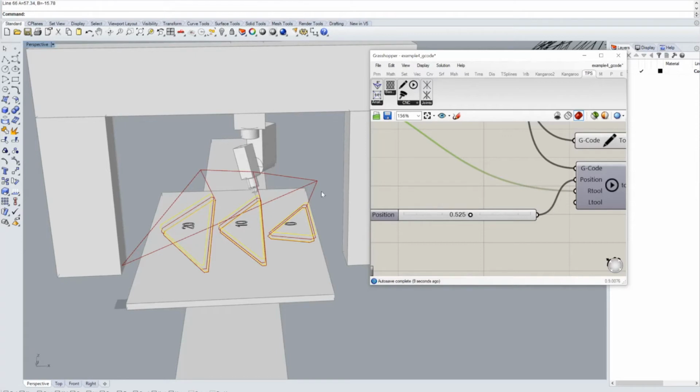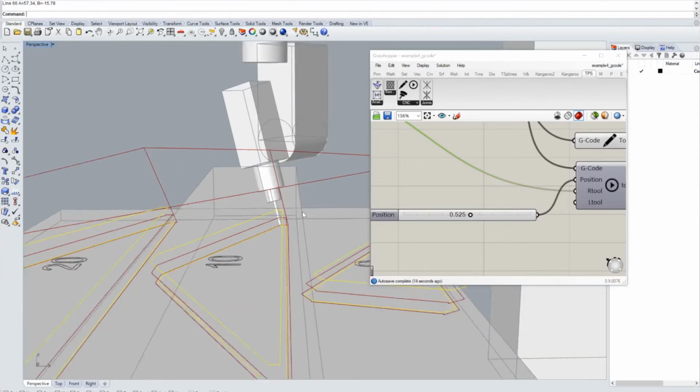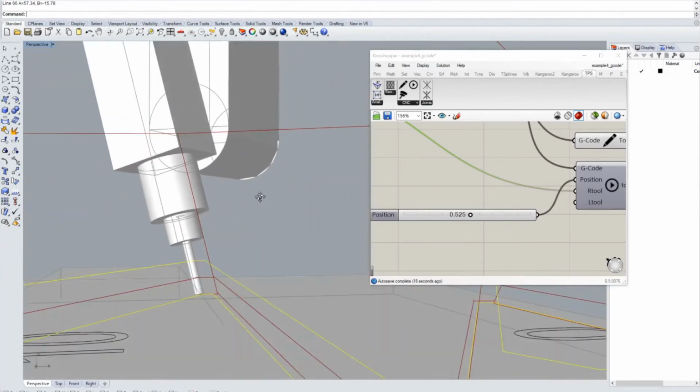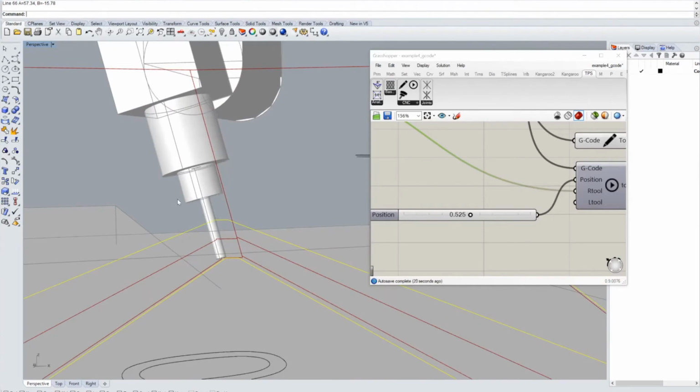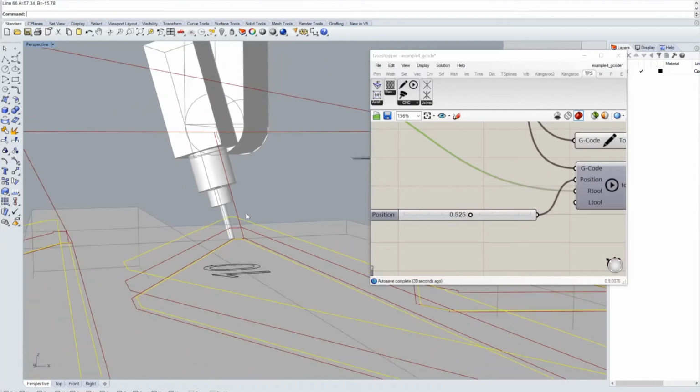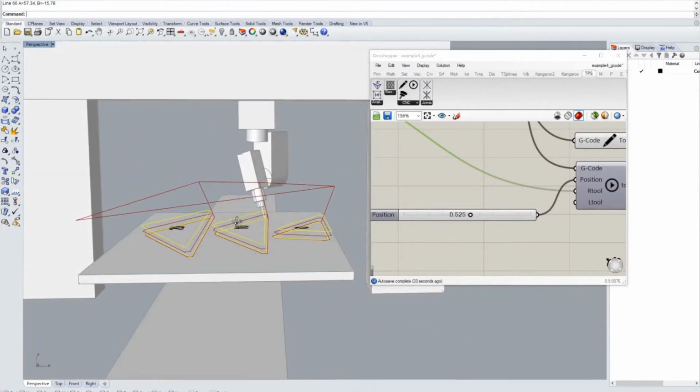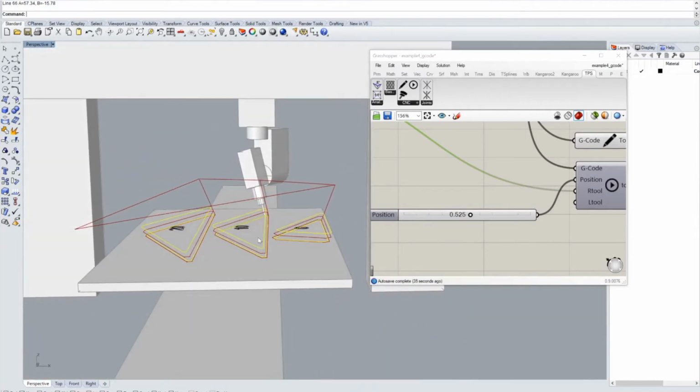Your machine on which you might be cutting this finally could look different from this one, although the most critical questions that you're typically asking is if it's going to collide with your tool holder. And this here is a 63 millimeter tool holder, which is a very common tool holder. So this should be very close to the setup that you're looking at if you do this milling with timber plates.